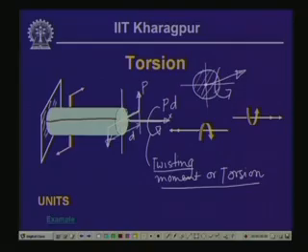In fact, before we go into that, let us look into another kind of loading which we have applied over here. Now, we have another load, let us say, applied in this particular form. This is also a couple acting at a distance, let us say d again. So, this is also going to cause a twisting moment, a moment about the axis along the length of the member, which is acting in a clockwise direction. So, this is also a twisting moment, but the direction of this is different from the direction of the first one. Now, let us look into these two directions and analyze them.